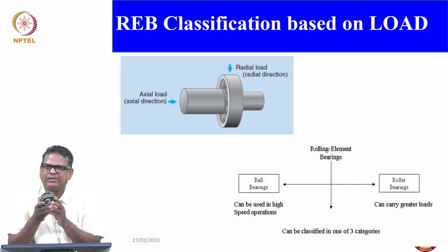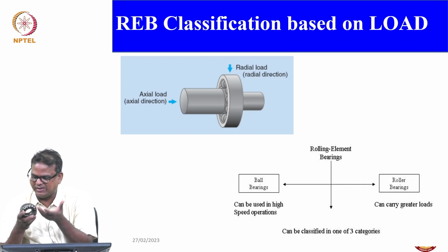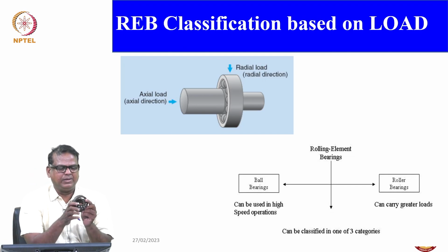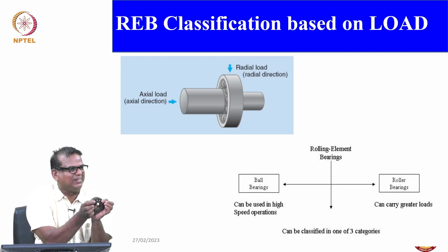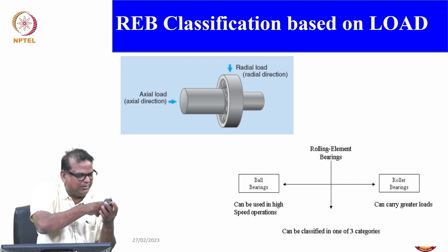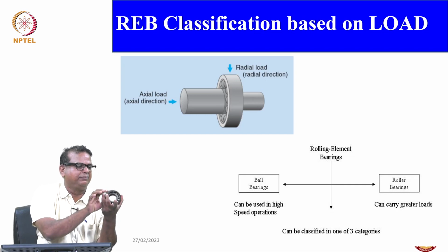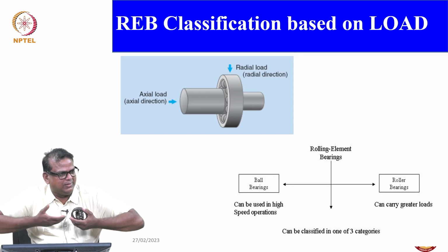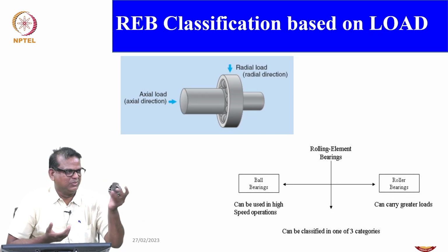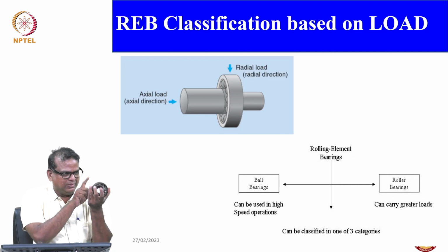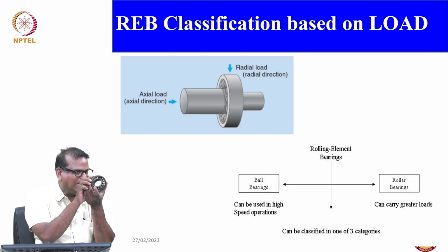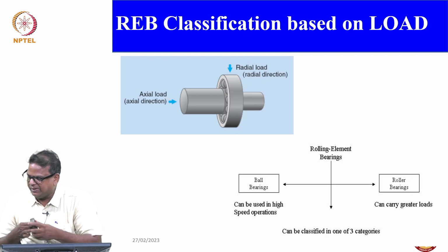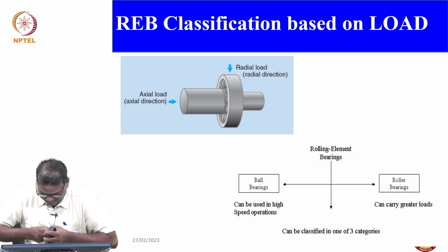In fact, there are so many types available, but I have only 3 bearings. At a later stage I can show other types also. You can see that you can rotate it. By giving that kind of flexibility, if you have 2 shafts that are not collinear, the misalignment can be taken out. So, that is the purpose. Not only that, it can withstand both radial as well as axial load. Yeah, this is the self aligning double row ball bearing.